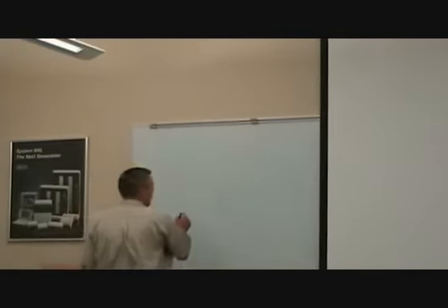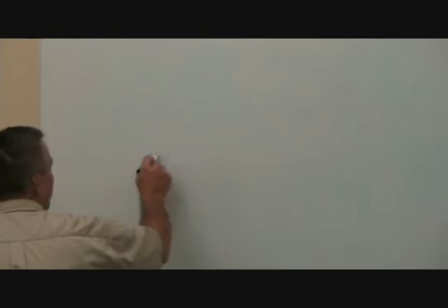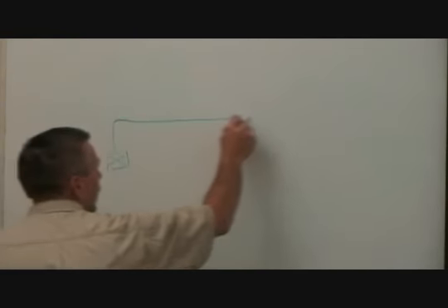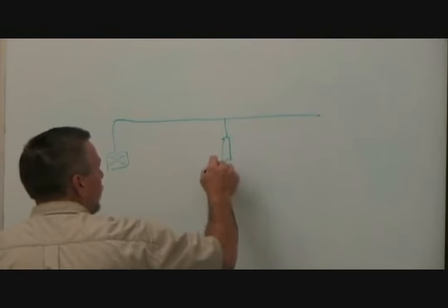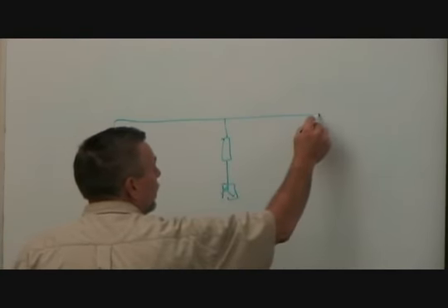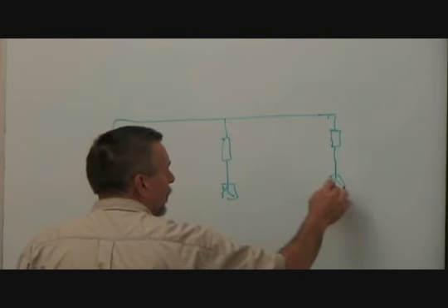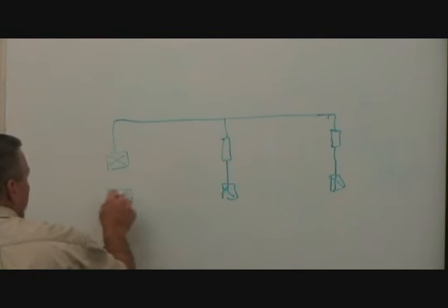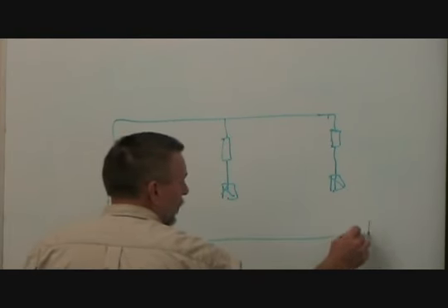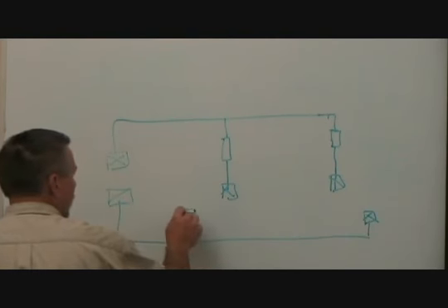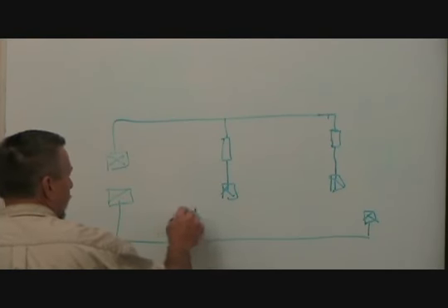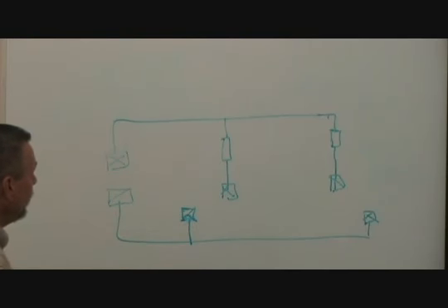Another thing I've got is mechanical room. Show you some piping layouts, how we've been talking about them. The other thing I was going to talk about in the air distribution, you got supply from an air handling unit, ductwork comes out, goes to a VAV terminal, goes to a diffuser. Turn comes back. Same method as in that pipe system.